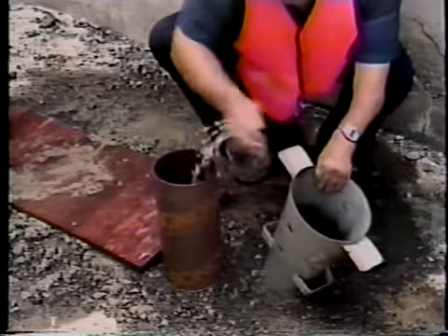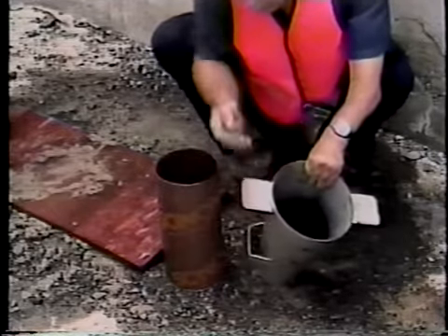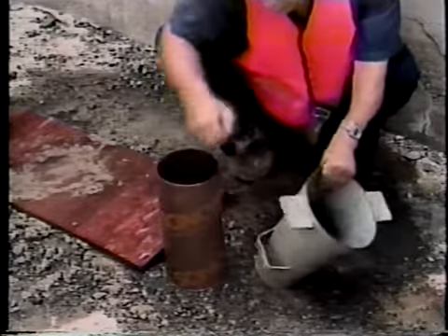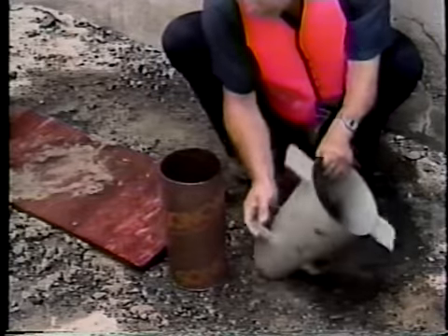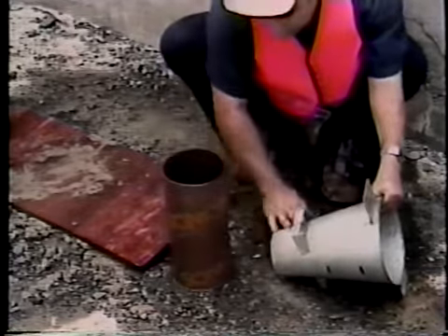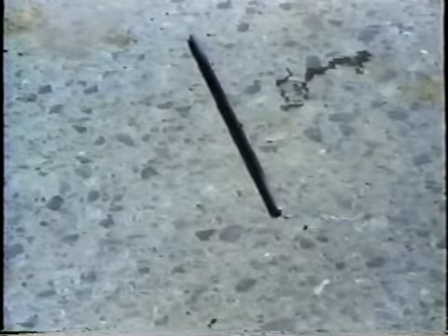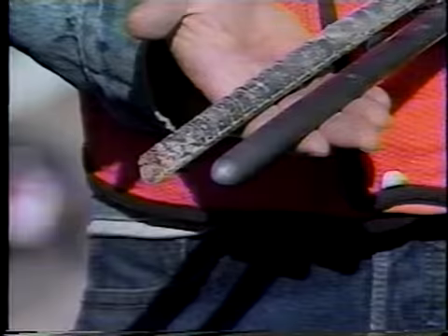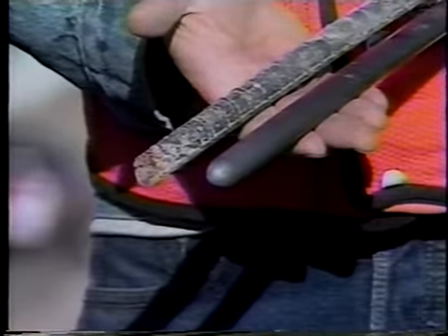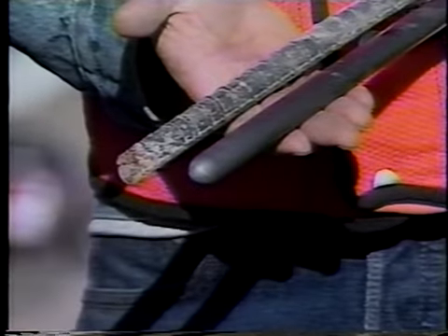The slump cone should be reasonably clean, especially inside. The surfaces should be smooth, with no dried concrete on them. Also, there should be no major dents. A standard tamping rod is smooth with a rounded tip. Makeshift rods, such as cut-off reinforcing bar, are unacceptable.